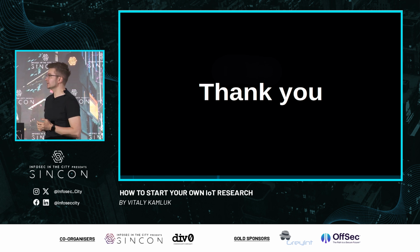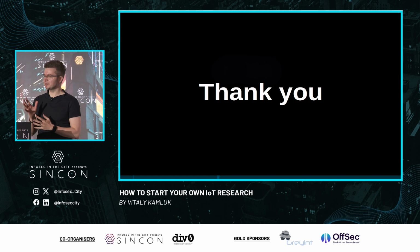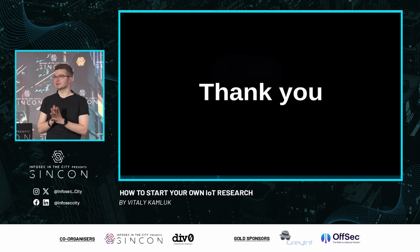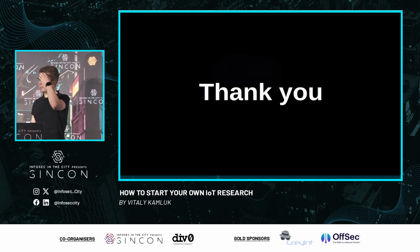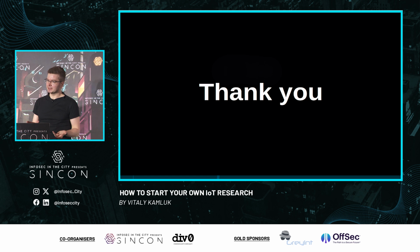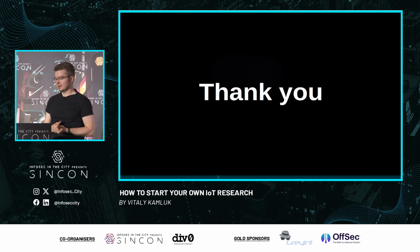Because once I got the firmware, I extracted things. There was some lack of clarity. It's a MIPS CPU after all. Reverse engineering that is a bit hard and new to me as well. So I thought, with reverse engineering, you can pretty much boost your speed if you have a dynamic approach at the same time as the static. If you have a debugger and the static disassembler, it is much, much faster. So this is where I started looking at how about the live shell? And I found that, yeah, there is a possibility. But it took some time to get it.